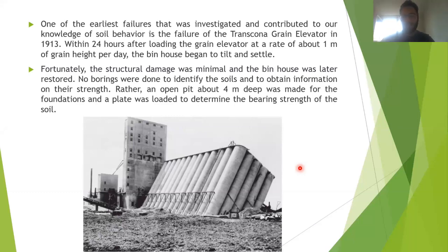That's the reason why you want a geologist on the site, just to see what kind of rocks there are. One important thing related to the chemical composition of soil is that different minerals in the soil can have a lot of effect on soil behavior.